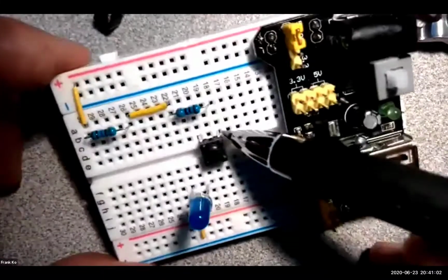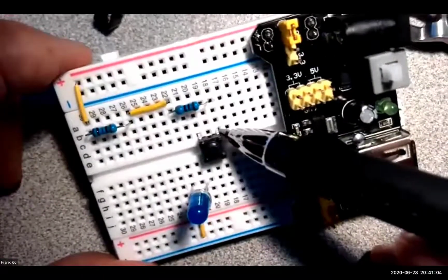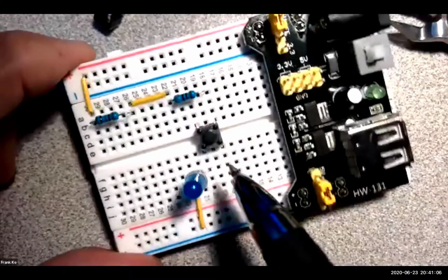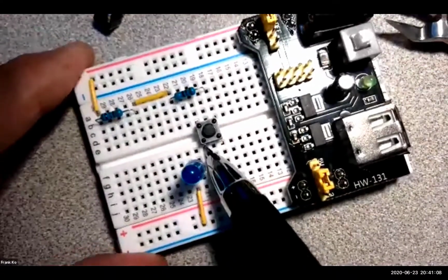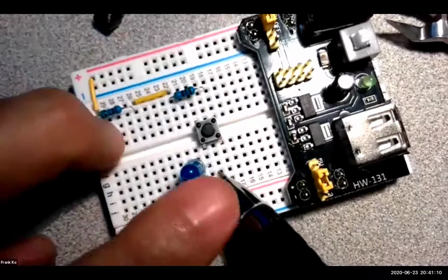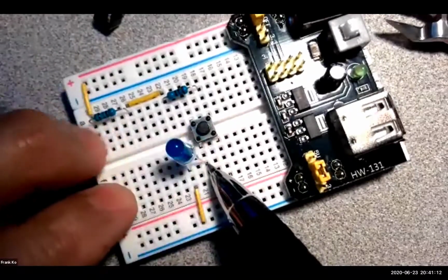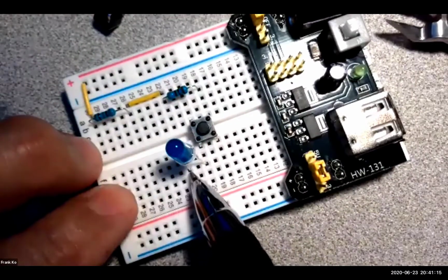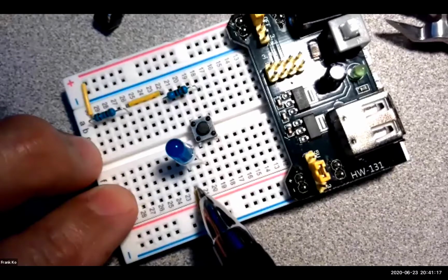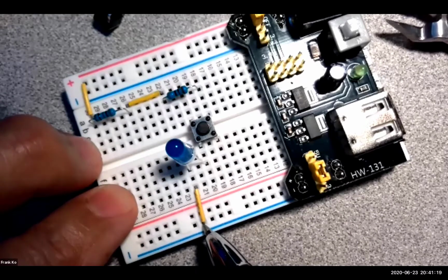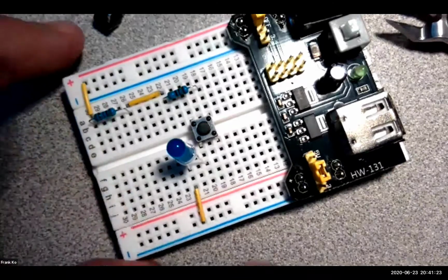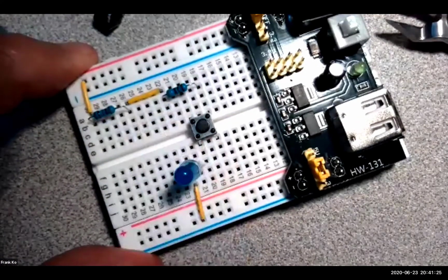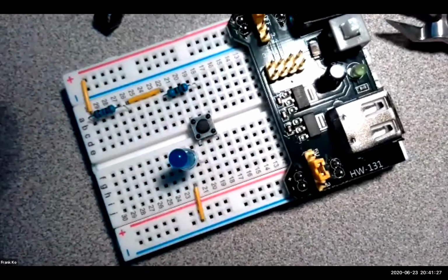It's connected to my switch at the upper right-hand pin. The lower left-hand pin on the other side of the dip groove is connected to my LED, long lead. The short lead of my LED is the negative side, which is connected to a last jumper to my negative side of my source, which is my blue rail. So everybody okay with how this guy is set up?